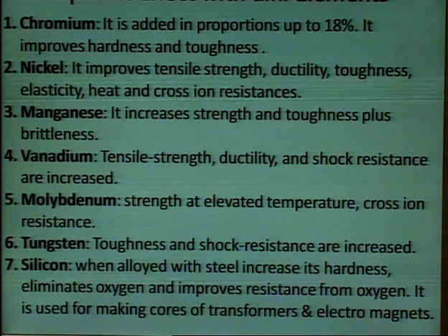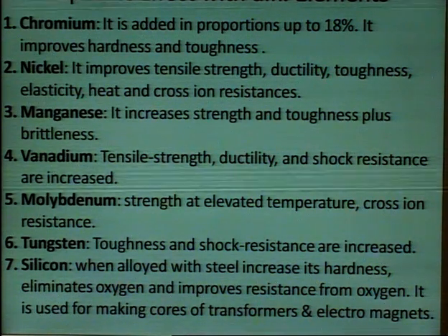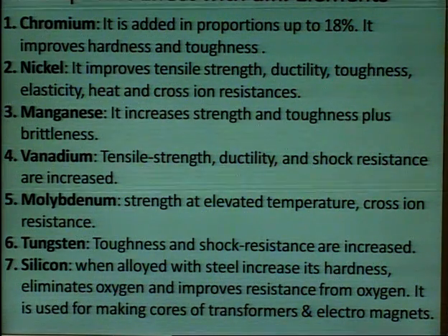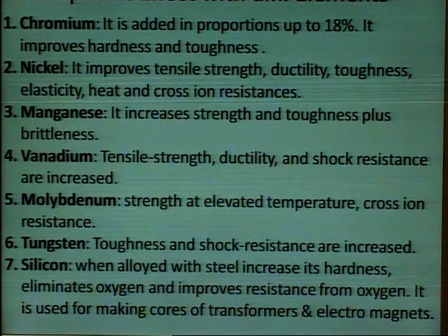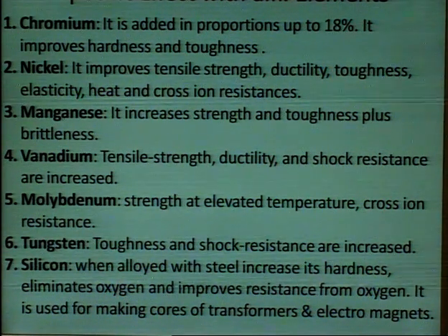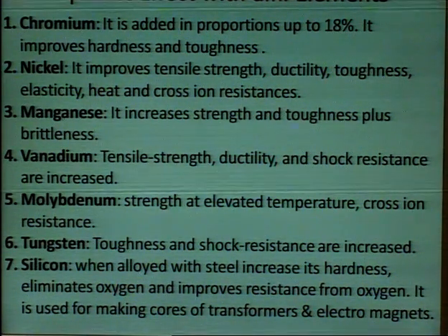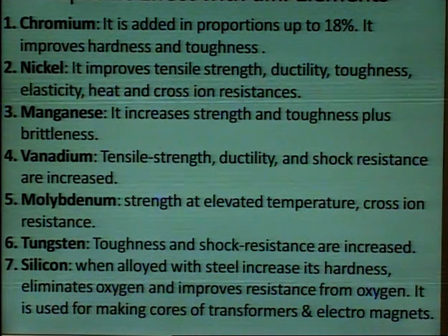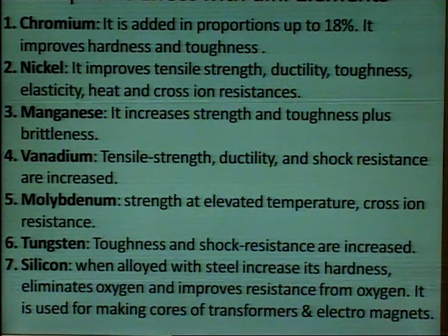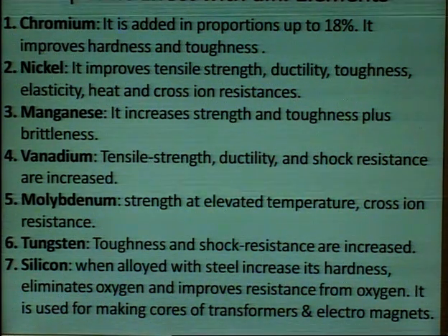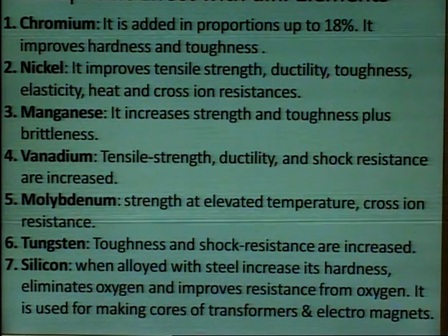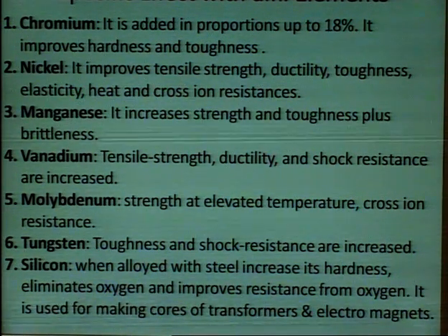and it improves the ductility, elasticity and heat and corrosion resistance. When iron is mixed with manganese, it increases strength and toughness and it also increases the brittleness. When iron is mixed with vanadium, it increases the tensile strength, ductility and shock resistance.